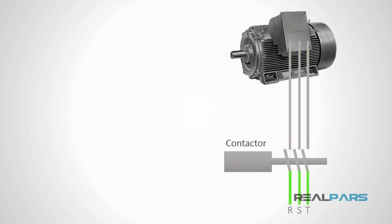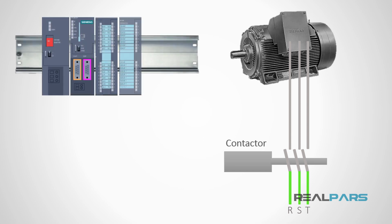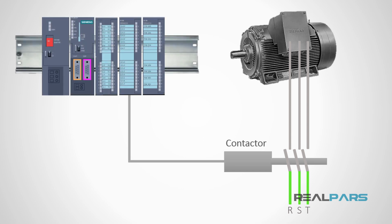We know that we need to apply a voltage to the contactor's coil, so the coil is the component that should receive our command. Now, in your experience, what is the most suitable equipment to use in order to command the coil? That's right, a PLC. We can install the PLC that we configured in previous lessons, connecting the contactor's coil to the PLC's output. This will allow the PLC to energize the coil by sending an electrical signal to it.